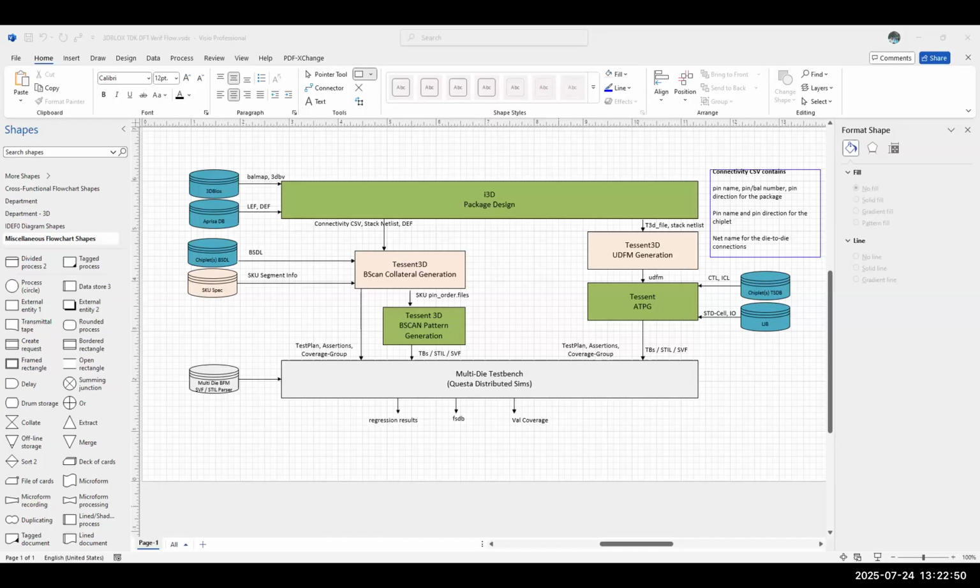Yeah. So there's kind of two dimensions to that. One of them is in the 3D block spec, and in fact, I would argue that's the only thing that's in the 3D block spec, which is basically the wafer sort pins. What pins does the OSAT need to test the part at wafer sort test? That's pretty straightforward, right? Here's all the probe pads. It's a list. You have the XY coordinates and pin names, and then there is a whole set of collateral that you would provide.